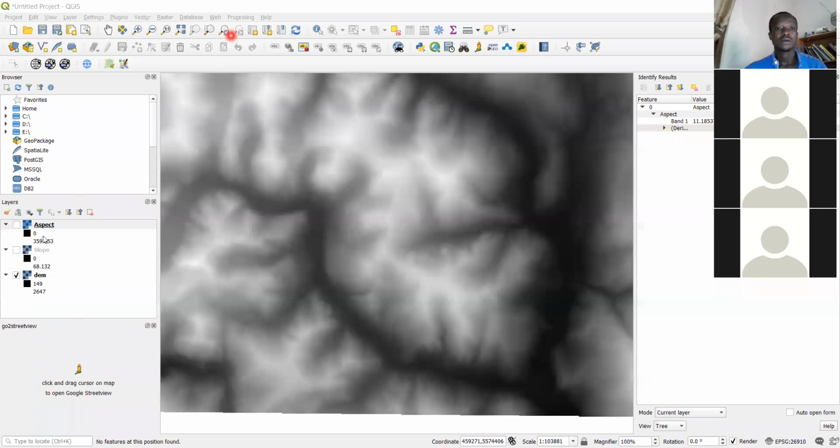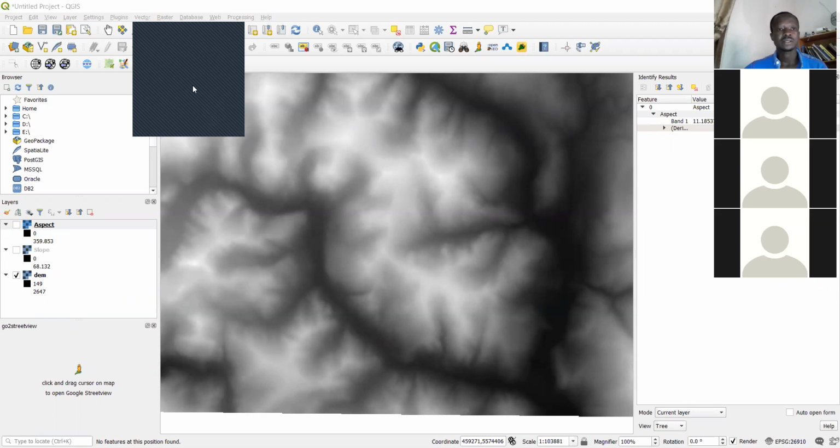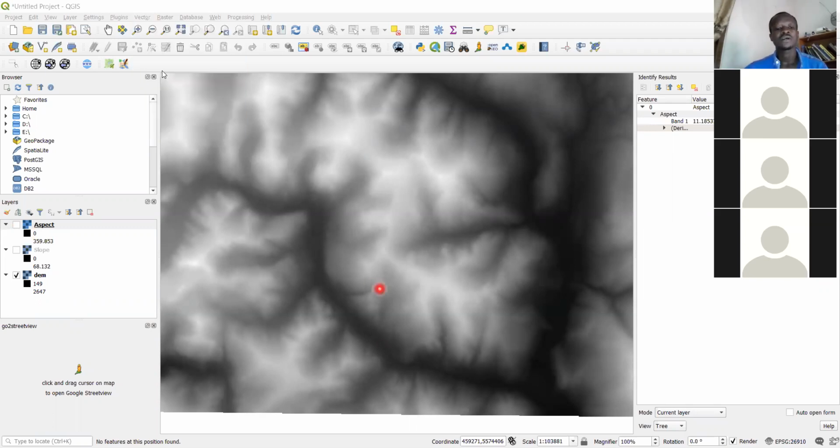All right. So now just add your road data and then click on vector, topology checker. Are you okay? We just want to see, play with it. And I told you that the topology is supposed to take care of overshoots and underhangs. Like I'm saying, there's no road around any intersection that goes and just ends. This is a dead end. How can you have a dead end in the middle of an intersection? It means that it's just a digitizing process that hasn't gone well. And we see a lot of dangles, lines that are just hanging.